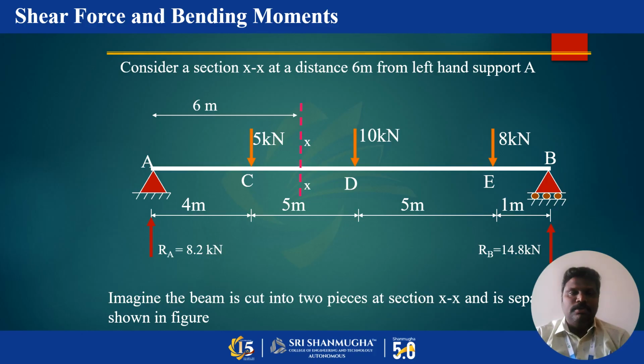Before getting into the topic: shear force is the algebraic sum of all vertical forces acting on a section, either to the left or to the right of the point. In this example, I have cut the section XX. The beam has a span of about 15 meters. Whatever vertical forces are acting on this beam, when I add them all, I can get the shear force either left of the section or right of the section. The value of shear force on either side of the section must be equal.